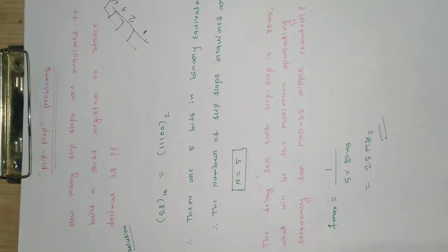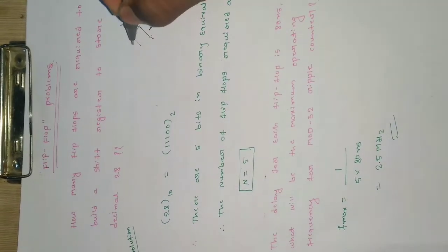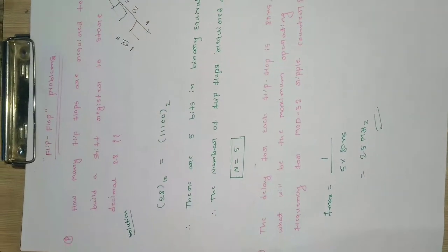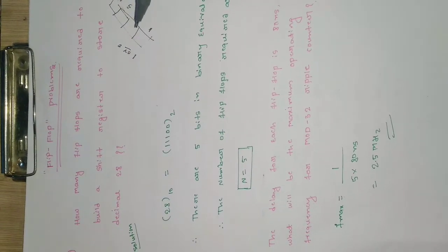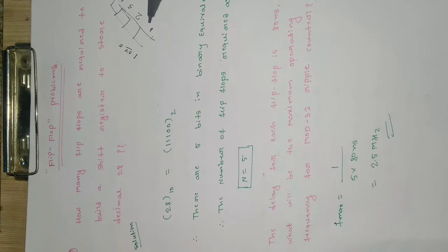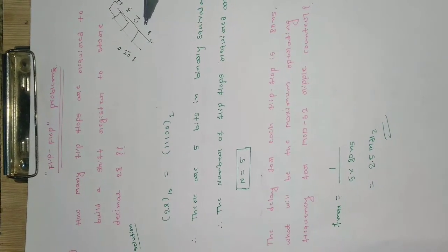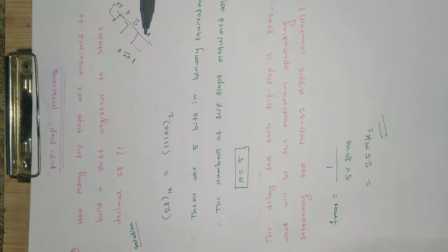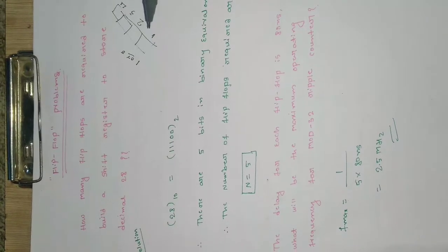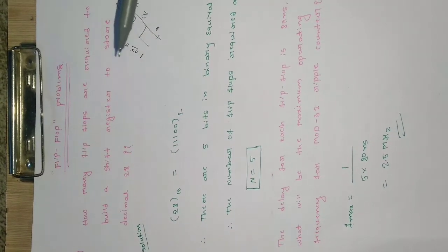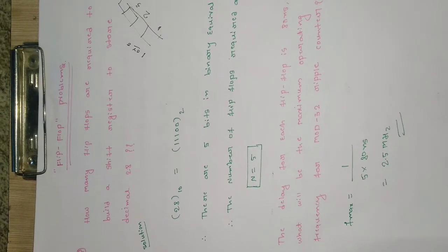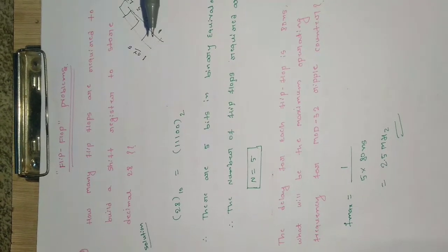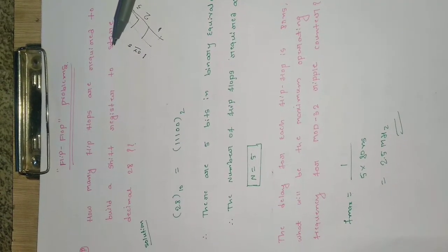Either it can store binary 1 or 0. So one flip-flop can store a maximum of 1 bit, and if you want to create a 4-bit register, then we need 4 flip-flops. Okay, so 1, 2, and 3. This is the general structure of how a shift register is built with the help of flip-flops. Now coming to our problem, here we have a decimal value 28 and we want to store it in the shift register. So we want to build a shift register, so we need flip-flops here.